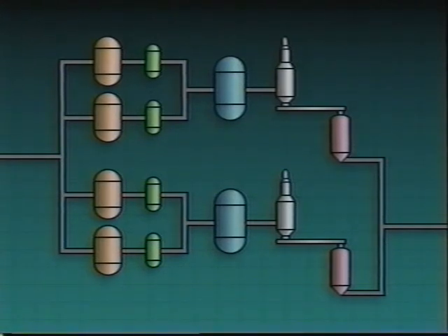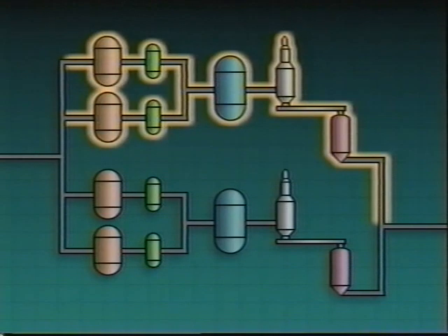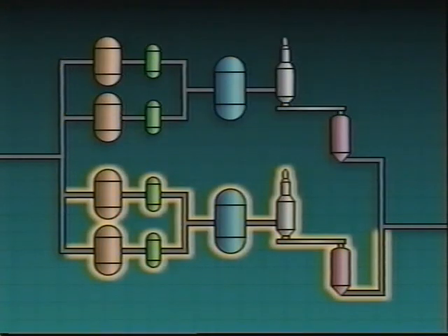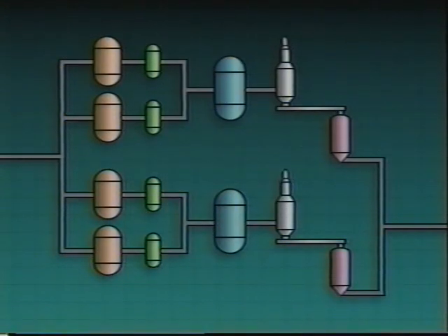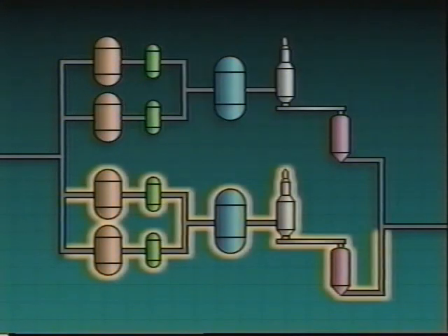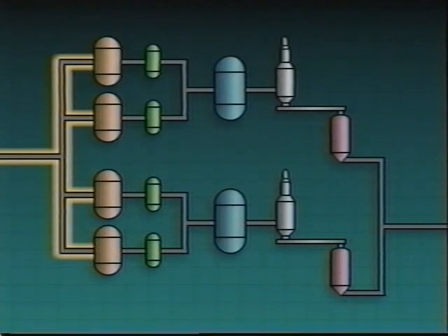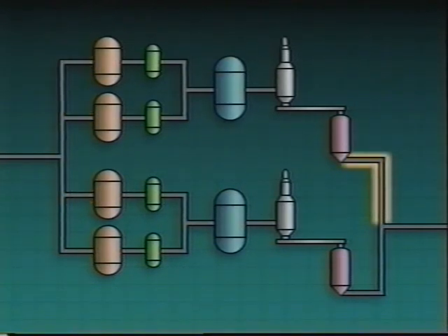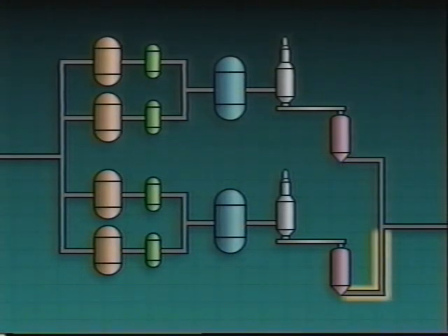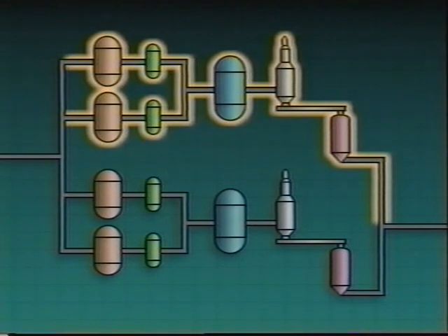This represents a polyethylene process, which has two reactor trains running in parallel. This means basically that the two reactor trains are producing the same product and at the same rate, but independently of each other. The equipment is the same for each train, and both trains process the same feed material. If the product from one of the reactor trains is off-spec, but the product from the other train is good, then we've bracketed the cause of the problem within this reactor train.